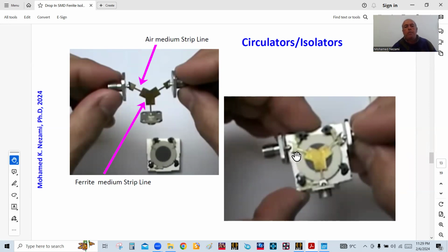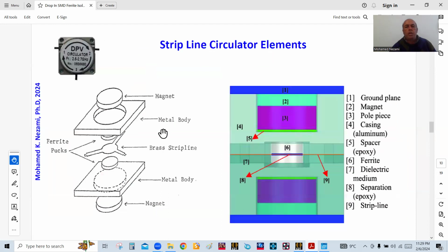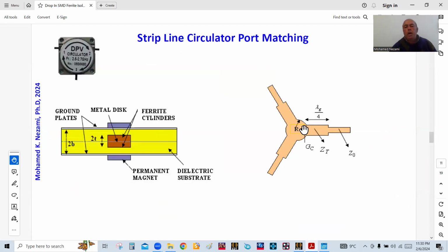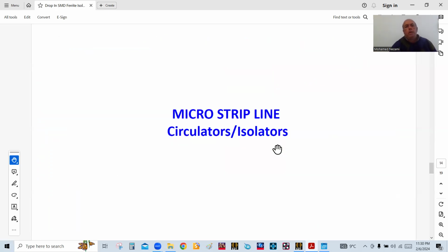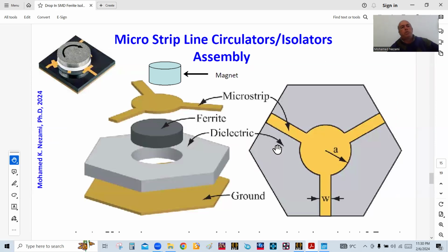So it's a little different, but in essence, what happens is you have the disc in here, you have the impedance at this plane reference in here, and you have 50 ohm in here. So what you need to do, just simple student level type circuit design, is insert a quarter wave line to do the impedance matching between these 2 ports, assuming they're fully resistive, okay? So let's go to the microstrip line.